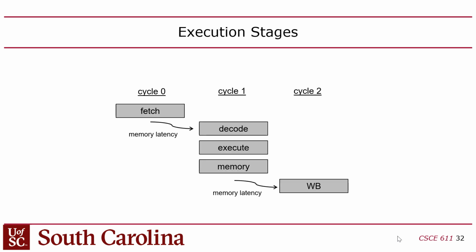In our case, the concept is that single cycle is too slow. Our CPU should be faster than our Arduino. To accomplish that, we're going to break up the execution into multiple cycles. We're going to execute each instruction over 3 cycles. We're going to fetch in 1 cycle. And by the way, if your instruction memory is synchronous, you have to fetch in 1 cycle. The only way to create a single cycle CPU is if your fetch is asynchronous, right? You have to be able to fetch within 1 cycle.